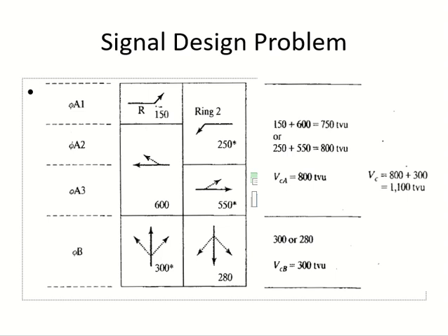So for a signal, this phasing plan is given. Now this diagram is called a ring diagram. You can see different movements are shown, and which phase has the movement is also shown. So A1 has two movements, left and this. A2 has what? The straight and the other left. A3 has what? Two straights. B has what? Two straights in the other direction.